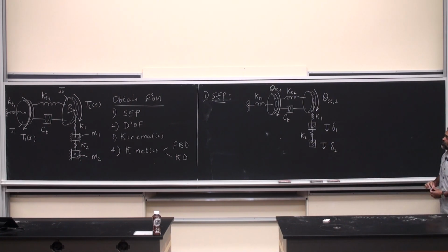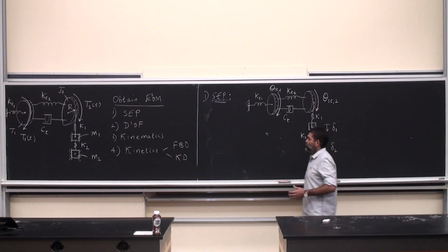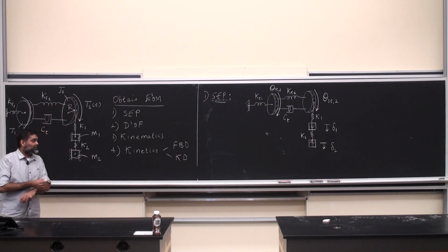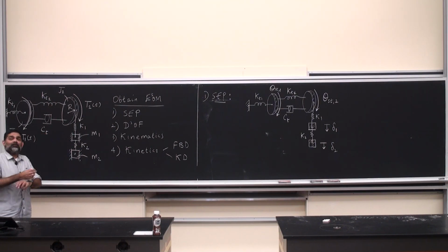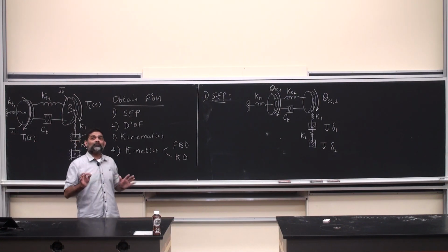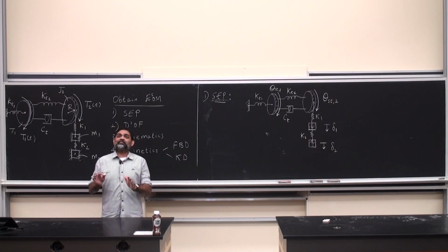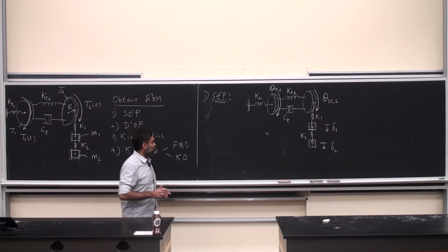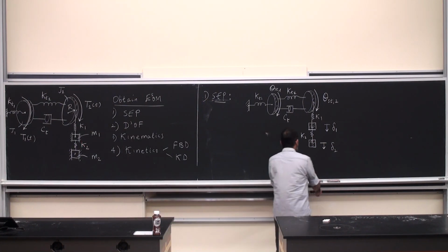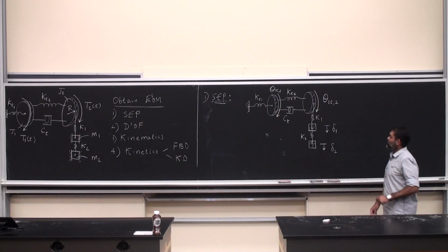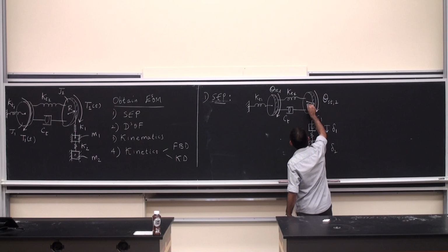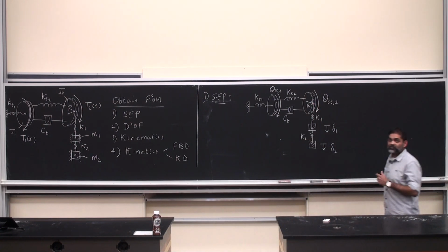Okay? And the idea is, first of all, what are these theta static 1, 2, delta 1 and delta 2? How do I even calculate them to begin with? And then, is everything in static equilibrium? Is everything in balance? That's the question that we seek to answer in an SCP analysis. Okay? So let's do that step by step. I'm going to look at the springs first. Let's call this distance R, all the way to the circumference of this second inertial element.